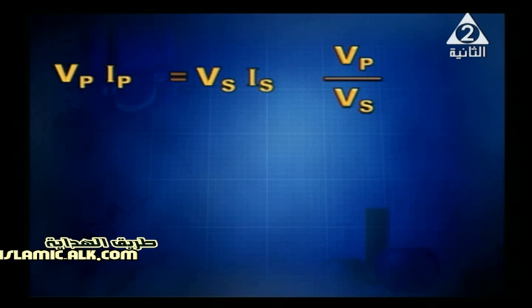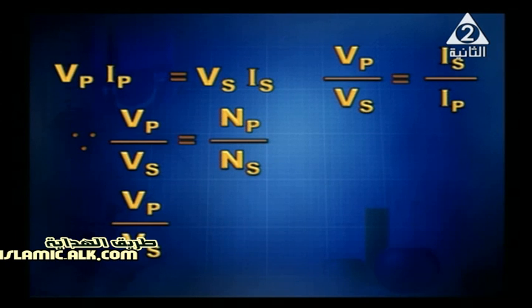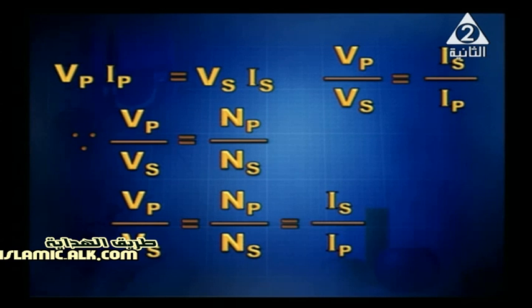So we can say Vp over Vs is equal to Is over Ip. So we've got an inverse relation between current and voltage. This means a device which is a step up for the voltage will be a step down for the current. So since Vp over Vs is equal to Np over Ns, it is equal to Is over Ip.